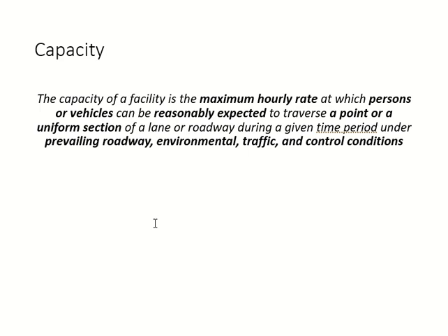Capacity can change according to road conditions. We have already mentioned lanes, width, shoulders. It can change according to environmental conditions: heavy rain, snow, fog. Okay, so capacity in these conditions is entirely different from a normal weather condition. Then traffic conditions. Traffic conditions mainly include the mix or the proportion of different types of vehicles. So if you have more percentage of trucks, capacity will be different as compared to when you have less percentage of trucks, because trucks are slower. Okay, and then you have the effect of motorcycles and other types of vehicles as well.